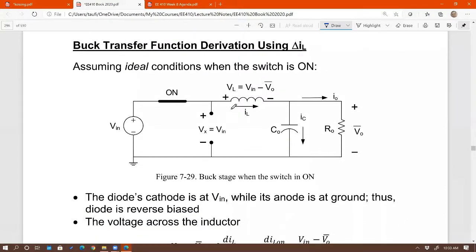All right, so I'm going to start with the buck converter again. Assuming ideal source, therefore I don't show the input capacitor. There are only two states of the buck converter, right? Either the switch is on or the switch is off, nothing else, right? So what happens when the switch is on? Remember this, there is actually a diode sitting right there, and there's a switch right here.